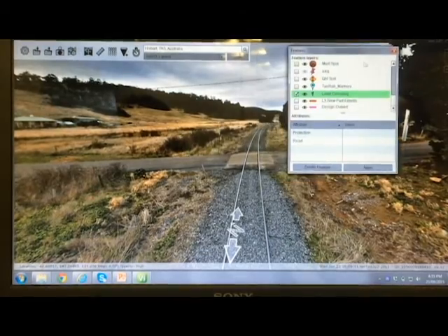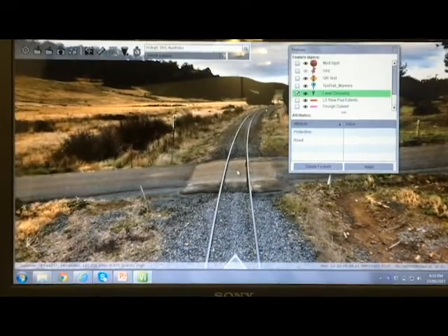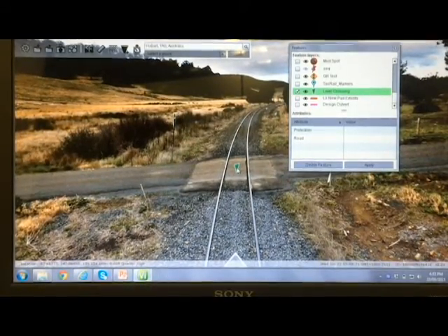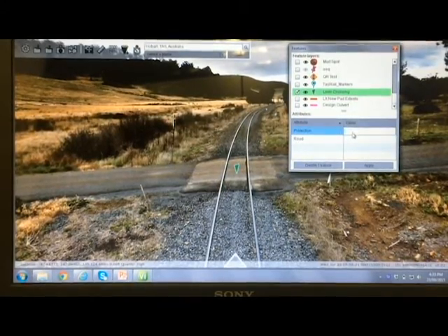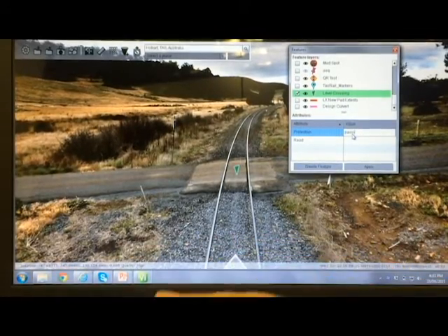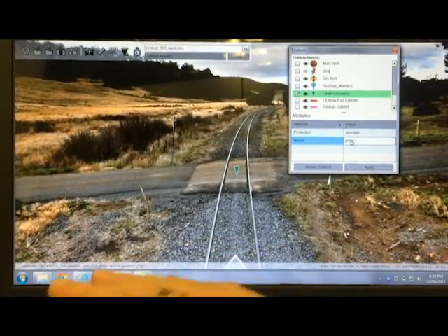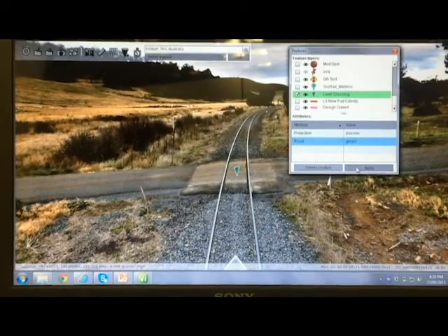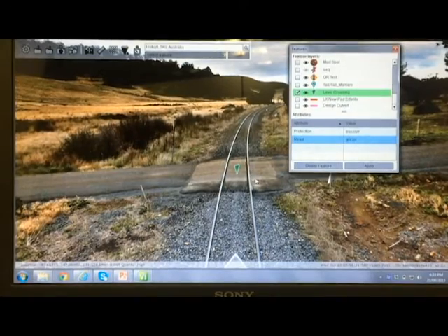minimising the map, and then navigating towards the centre of the level crossing, we can then place a tag at that level crossing location that automatically saves a coordinate to the file and then prompts the user to complete some basic attribute information that has already been set up. Once the level crossing has been mapped, the symbol stays within that panoramic as users navigate around the network.